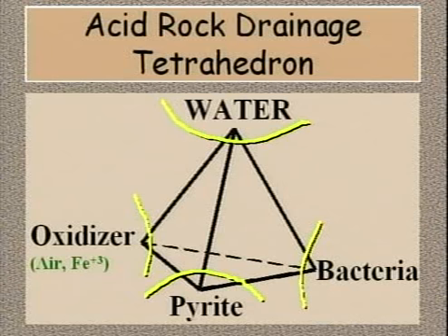So why is water so important? Many mineral processing operations use lots of water. This ranges from the heap leaching, where recirculated solutions dissolve gold, to conventional mills where rock water mixtures or slurries are found. A lot of water is tied up in the mine wastes themselves after the processing, and the subsequent rainfall can add to it. One way to combat ARD is to minimize the storage of water in the wastes. The old mining adage to store solids, not water, is especially appropriate because water is so difficult to control once it's been contaminated. Thus, any process that drains water or dries out the waste is ultimately beneficial.